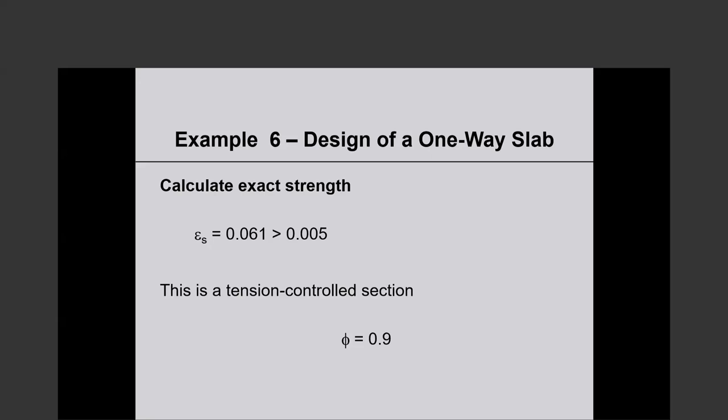High strength reinforcement requires high strength concrete if you are going to get full value out of it. With low strength concrete, you will not be utilizing the high strength of the reinforcement. The stresses that you will be imposing on the reinforcement will be significantly lower than the stresses that reinforcement can resist. So it is allowed, but it is inefficient.